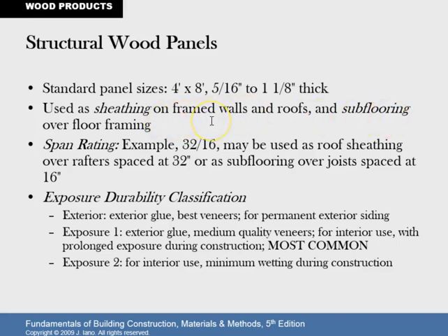Span ratings: the thickness is accounted for when determining how far between rafters a material like this could span. So should the rafters or the floor joists be at 16 inches on center, or would they be at 24 inches on center? The structural engineer or the architect would provide all of this information essentially. So if the span is X, then we need a thickness that is Y, for instance.